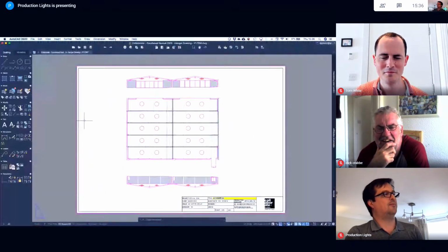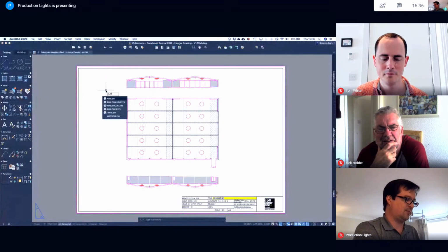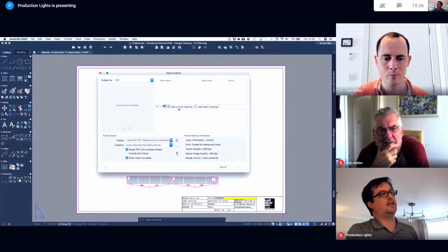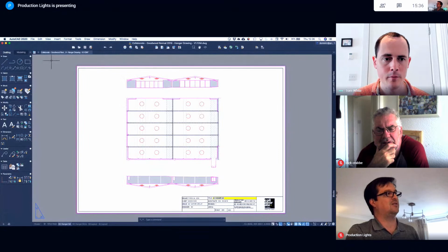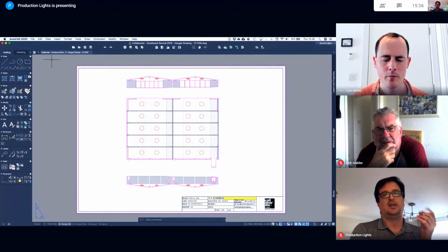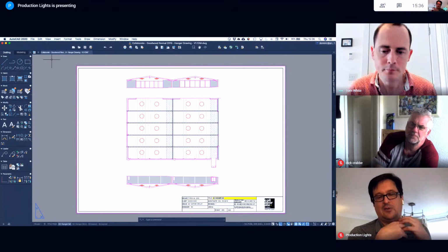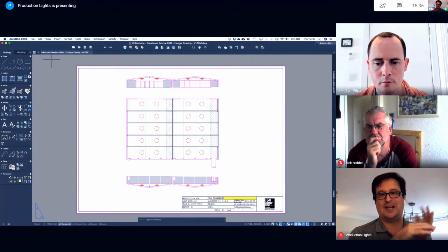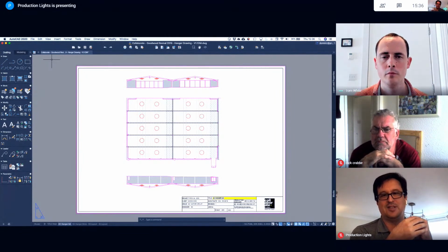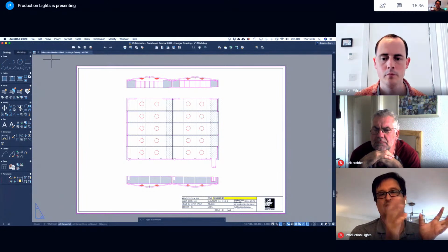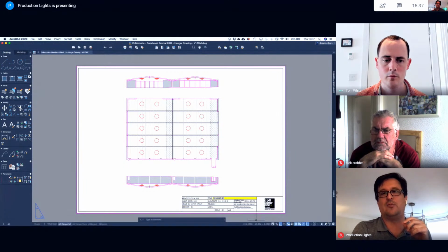What else to tell you? So like Vectorworks, we come back into publish. We can add the current drawing, and if you had other drawings open, it would then drag those in. So exactly like I did in Vectorworks, say we're in the theatre, and I want to do a general floor planning layout and send that, and I want to do the rigging overseeing drawing and the carpet plans, but they're actually sitting in 3 separate CAD files. I can open up those 3 CAD files, and then I can pull in the layouts I want, and then hit publish, choose a title page off one of them, and we're all good to go.